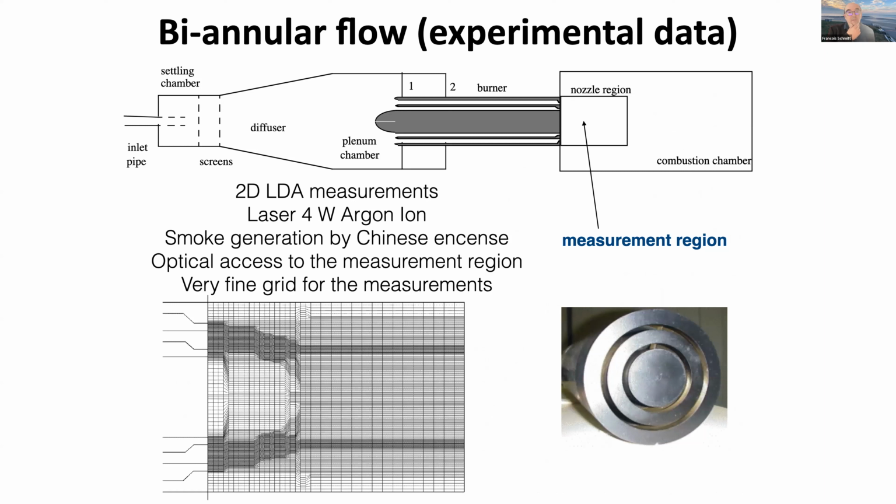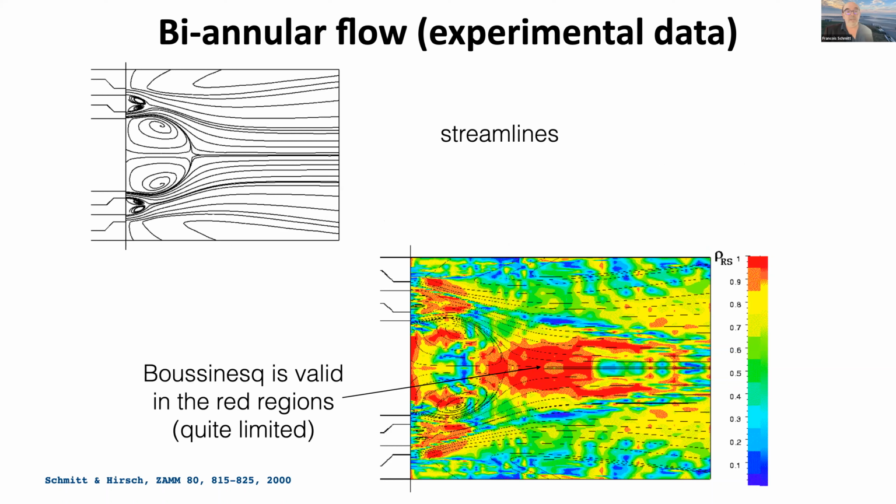This can also be done using experimental data. Usually, using experimental data, you can obtain the Reynolds stress very easily for each grid point. And the strain can be obtained, in fact, if we have a good grid and if we can make an approximation of the gradient. It's what has been done here for this experiment. And those strain lines are shown here. And the indicator is shown as a color code.